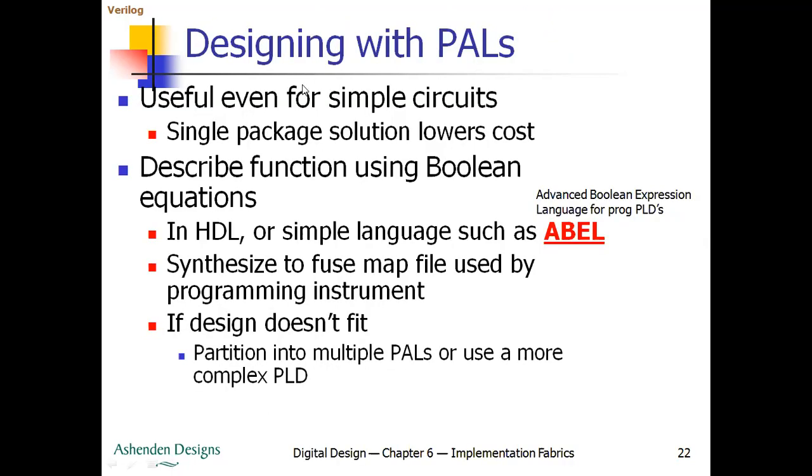These PALs are useful for simple circuit designing, and are a single package solution having the lowest cost, and you can describe any Boolean equations. For that, I can use an HDL or simple language like ABEL, a hardware description language whose long form is Advanced Boolean Expression Language for programming programmable logic devices.